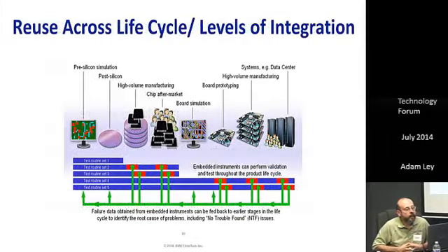Another thing to consider is reuse across the life cycle. One thing that we haven't talked much about, but it's worth emphasizing, is that intrusive test methodologies are inherently not life cycle portable. You can't take the wafer prober that you use for chip test and reuse it at the board level, much less at the system level. You can't take the in-circuit tester that you use for board structural test and use it in the field. But the non-intrusive methodologies based on embedded instrumentation can be deployed throughout the life cycle of the system.